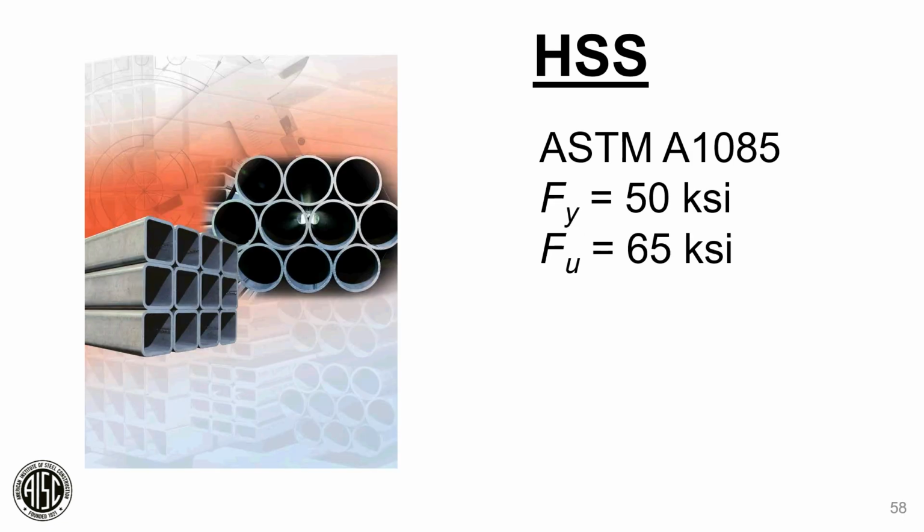A newer ASTM standard for HSS shapes is ASTM A1085. Now if you notice, this has the same yield as the A500 grade C, 50 KSI. But there are some differences.